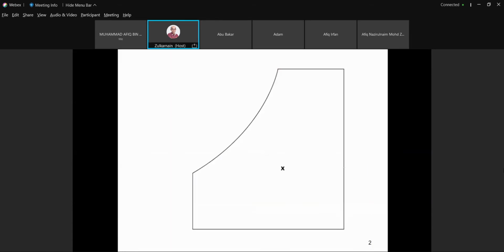And this can be elaborated a bit more on this diagram. So this is humidifying going upward from X to A, and then from X to B is dehumidifying. From X to C is the cooling process, and then from X to D is the heating process. So these are very basic processes, whereby if you look at the cooling and heating, omega is constant, while in the humidifying and dehumidifying, the dry bulb temperature is constant.